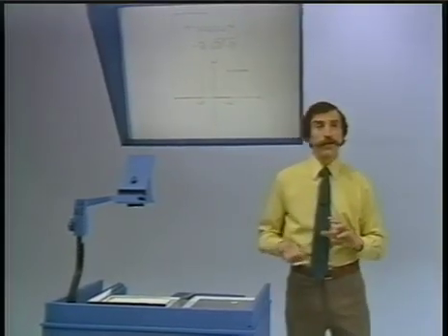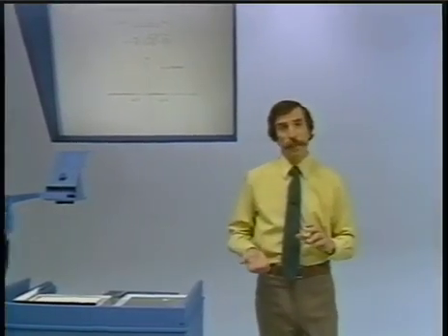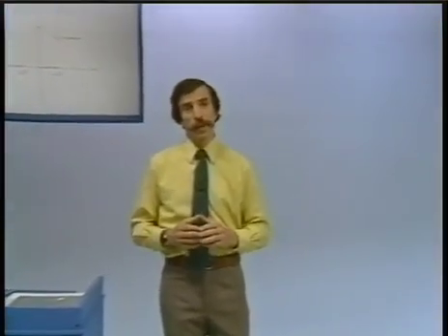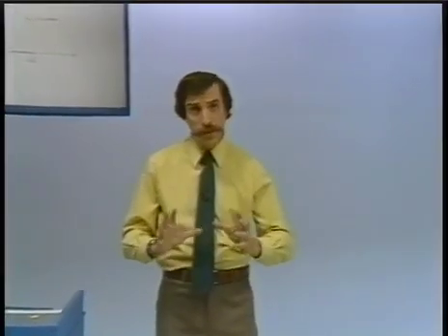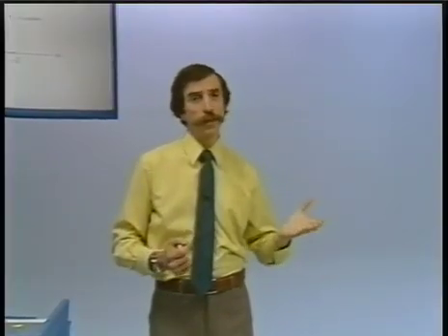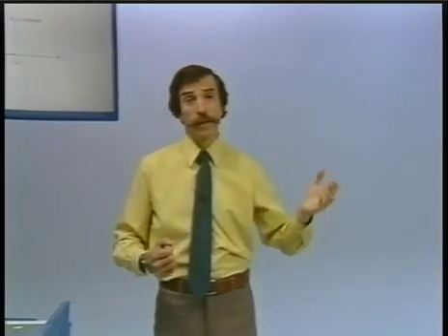So what we found is that with proportional feedback, we can't stabilize the system. With derivative feedback, we can't stabilize the system by themselves. A logical next choice is to see if we can stabilize the system by both measuring the angle and at the same time being careful to be responsive to how fast that angle is changing, so that if it's changing too fast, we can move the cart or our hand under the inverted pendulum more quickly.